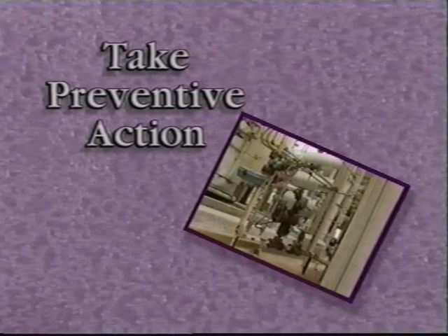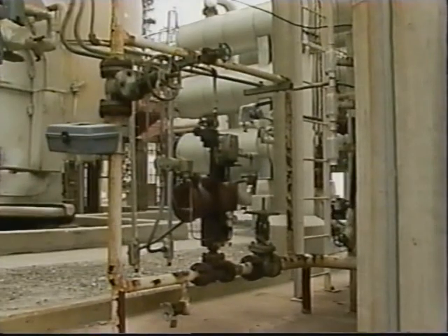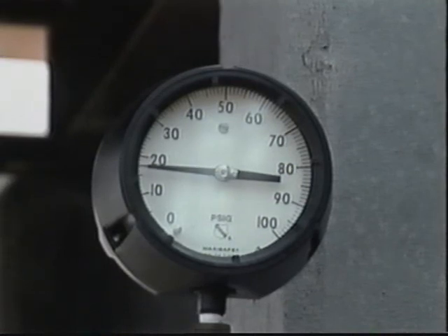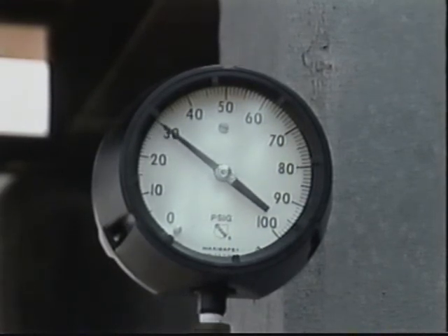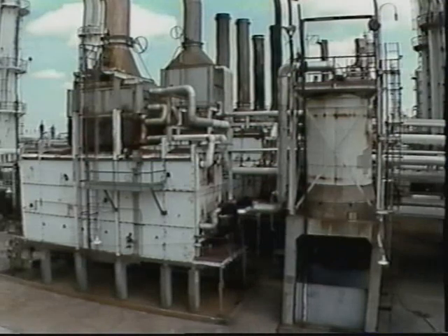While the problem is investigated, the control valve can be bypassed and the header pressure can be increased by operating the furnace under hand control. For this procedure, this manual bypass valve will be opened as these block valves are closed. This temporary step seems to do the job. Header pressure is brought back up to a normal indication. Shortly, the outlet temperature of the process fluid also returns to normal.